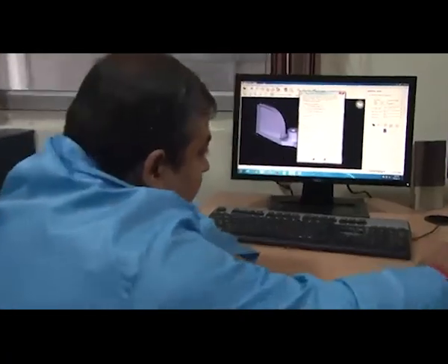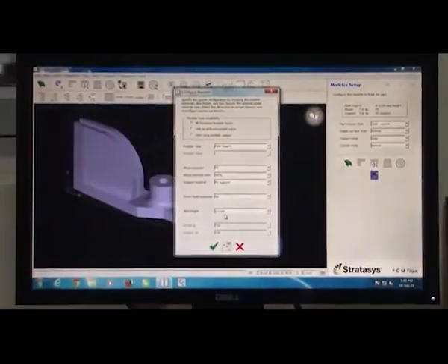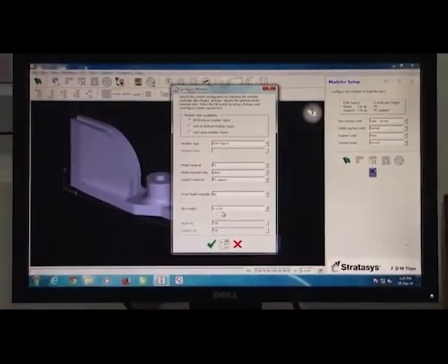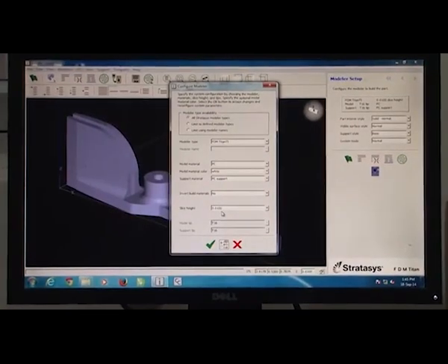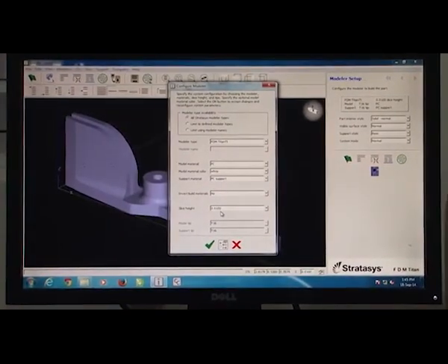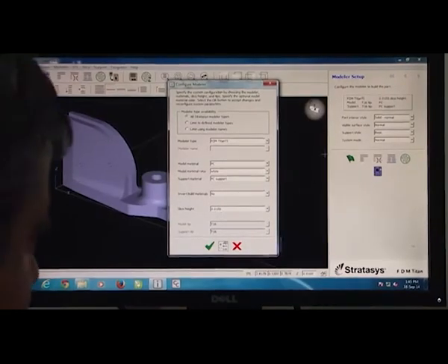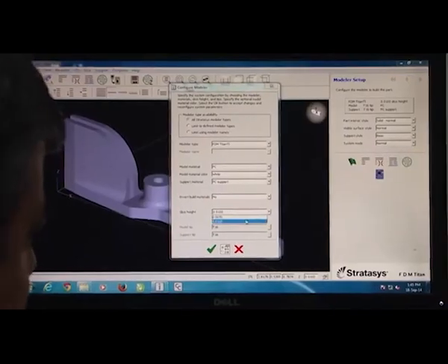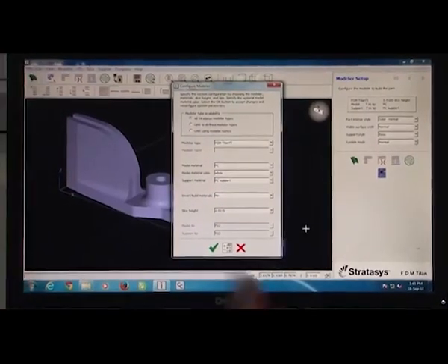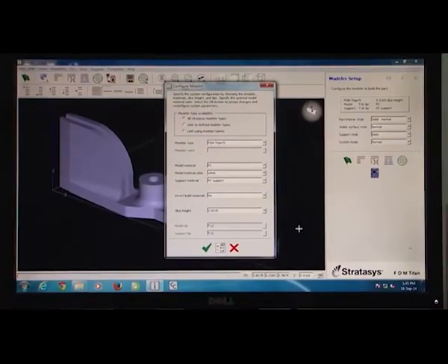And automatically, if you select this 0.01 option, the T16 nozzle is selected, which means that this would be able to handle and dispense the 250 microns layer. So T16 is probably a slightly thicker diameter nozzle, which exists in this particular case. If you had selected 0.007 as given earlier here, then you will automatically see that T12 is being selected. That means a lower size orifice nozzle is selected in that particular case.